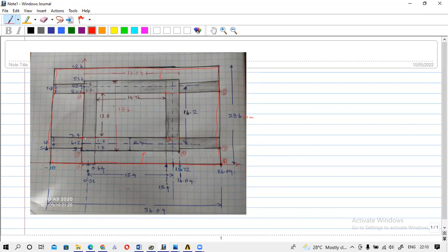You can find this point's x value and y value. For example, here the x value is 7.4, because we have given a 5 millimeter gap and the low impedance transmission line section is 2.4, so we get 7.4. In the same manner you can find this point also, that is 7.4 plus 13.8.